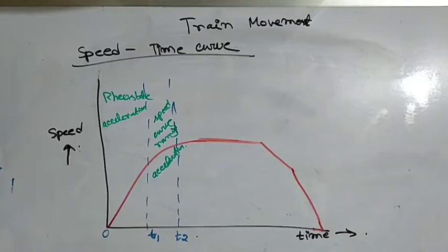And third, as the speed increases, the coefficient of adhesion decreases, and therefore the portion of the torque exerted by the motor which is usefully converted to tractive effort is reduced. The speed of the train will continue to increase to a speed at which tractive effort is equal to the train resistance, and the train then will continue to run at maximum speed.